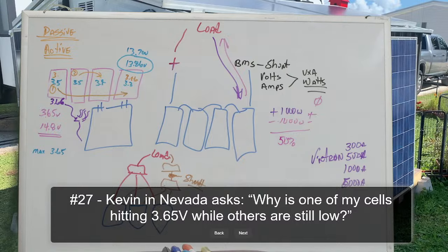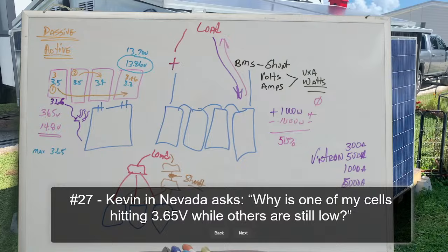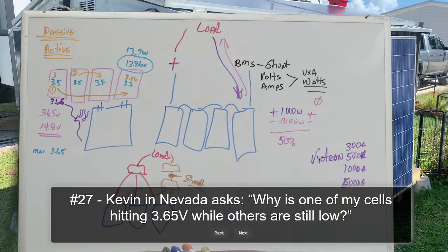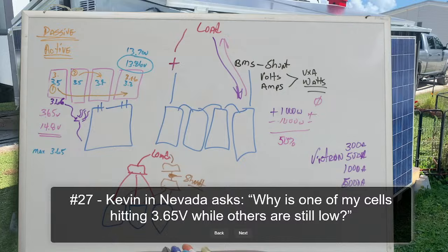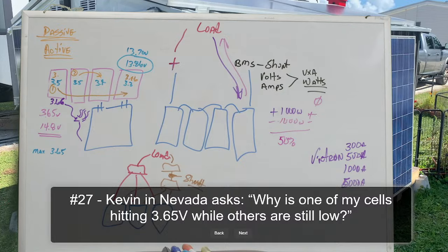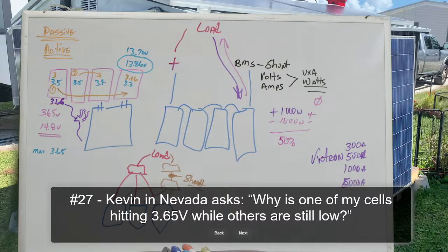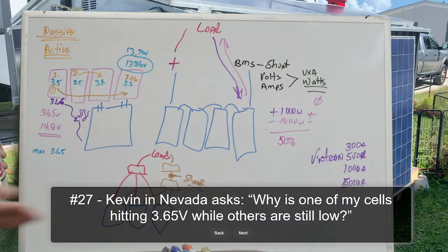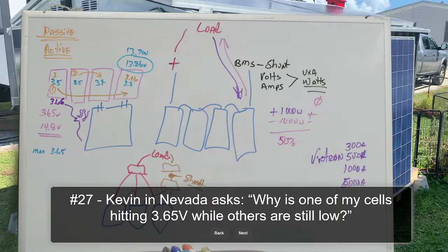So 3.4 volts basically puts your battery voltage on a 48 volt battery at 54.4. So you probably could set your charge voltage down at 55.8 or 55, or even 56 instead of, if you're charging at 56.2 or 56.8 or 57 or even 58. You just lower that voltage to where it is the highest it can handle before the BMS cuts you off.